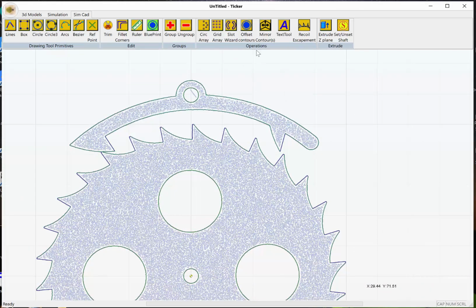And what we can do is draw a circle to act as a cap. You can see when I hover my mouse, I'll get a CC on the screen when I'm at the center of that hole that was already in that shaft. And I'm just going to drag this fairly large to about there. I'll right click and use my check to turn off my tool.